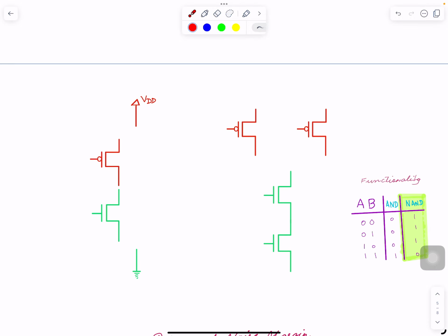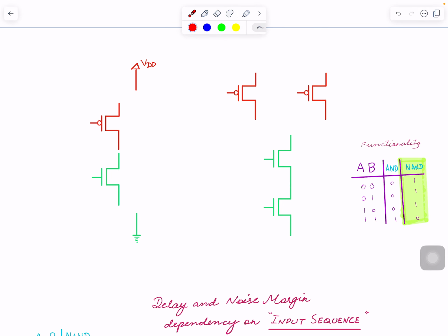So let's make a different circuit, and we are making a NAND here. What we do is, I was thinking of which way I go. Let's do this. A NAND is this, right? When you have 0 0, an AND case is 0; 0 1, 0; 1 0, 0; 1 1, 1. Then the NAND is the opposite. Here is something important. A B, and this is A B, this is A B bar.